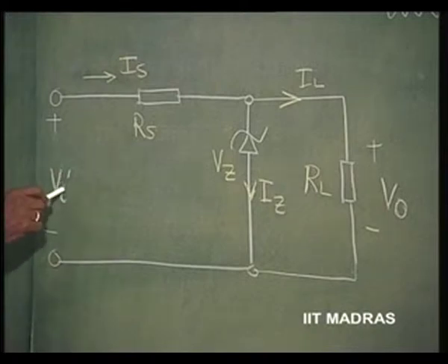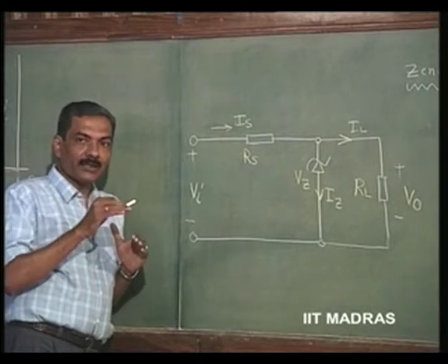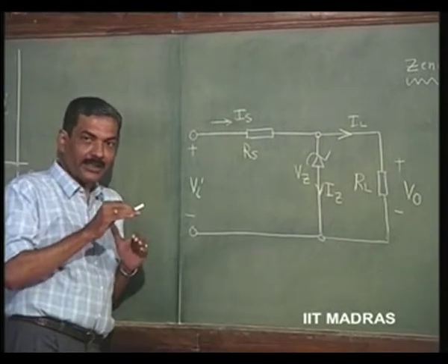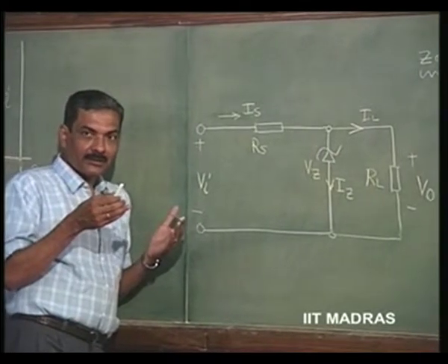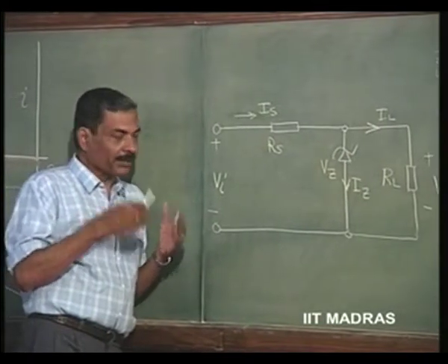So, this is the output of such an AC to DC converter, which obviously responds to input variations. If the input AC varies, the output DC will correspondingly vary, and therefore we do not want this DC voltage to vary. We want a DC voltage which is going to remain constant, so that we can use this constant voltage in biasing all our active devices later, so that we can do the design properly.